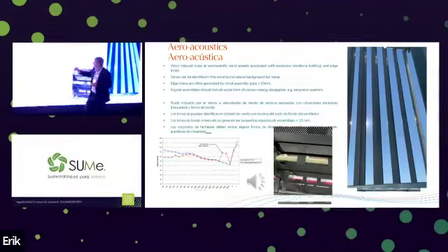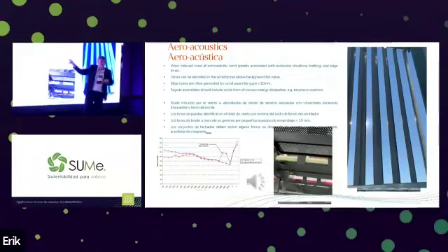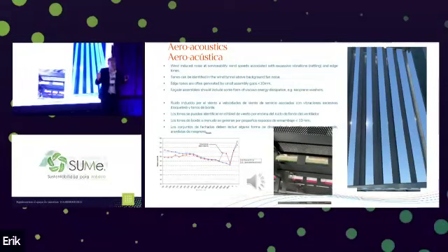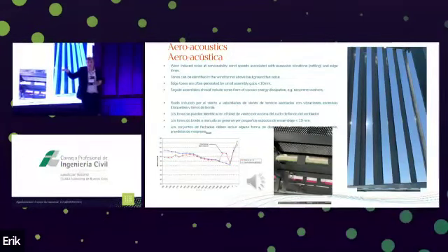And the other piece of advice is include viscous energy dissipation somehow. There might be neoprene washers, but something to absorb the energy. Otherwise, there's no way. You can't just go back to the slab and hope that's going to absorb the noise. It just won't happen.